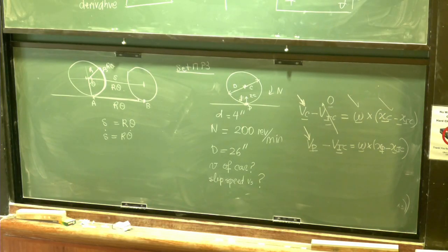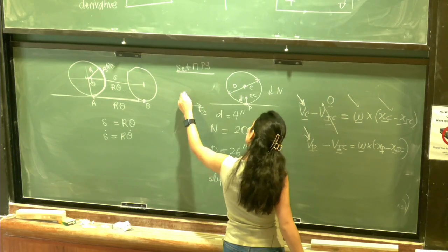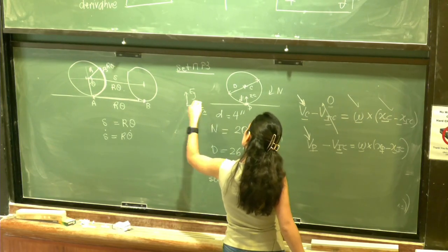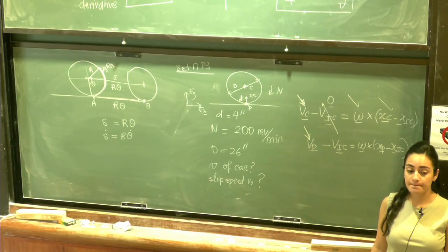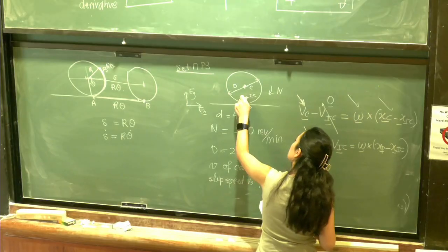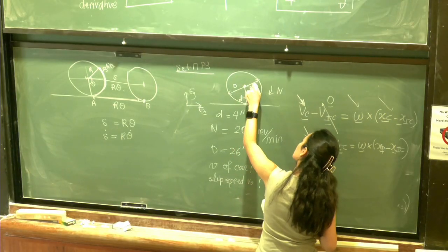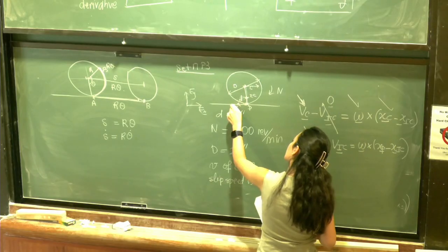That's it. So what do you think the direction of the slip speed is going to be? Along positive Ex or negative Ex? If I take Ex anywhere like this. What do you think the direction of the slip speed is going to be? Negative, right? So the IC is here. The car is going to the front. And this tire is slipping to the back a little bit, vx.